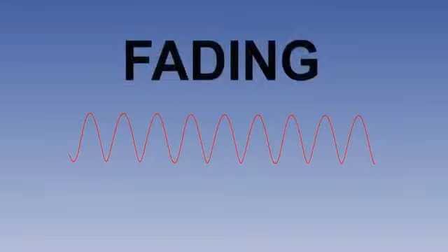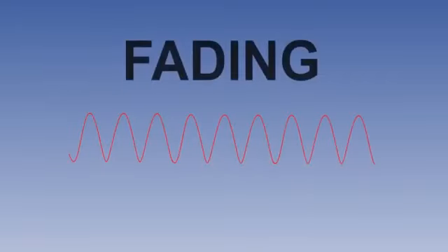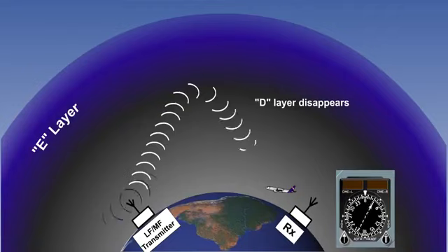Lastly, in this lesson, let us consider fading, which is the most troublesome problem when receiving radio signals, and it is caused by variations in signal strength because of distance, low transmission power, weather, terrain, and signal to aerial polarization matching. Multipath fading occurs when sky waves contaminate surface waves in the low frequency and medium frequency bands.